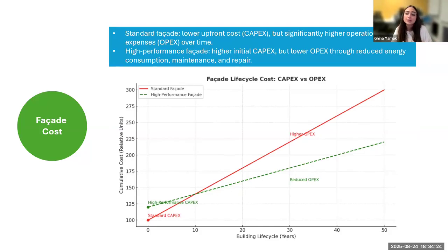So, and of course the testing and the commissioning. Now the facade is not a small item. It usually makes up to 20 to 25%. However, the OPEX cost, or the operational cost, is the cost of running and maintaining the facade through the life of the building. That means cleaning, maintenance, replacement of sealing, regular inspections and repair.